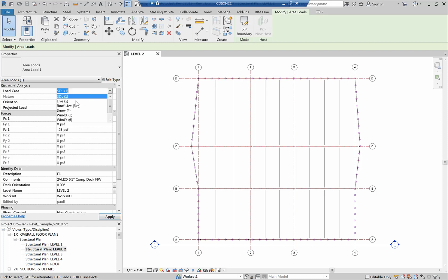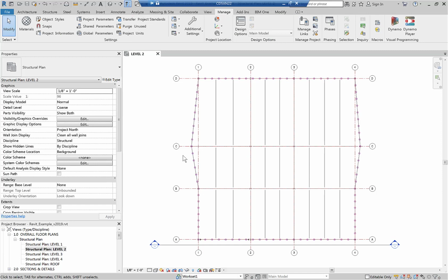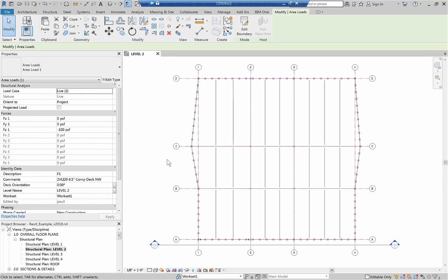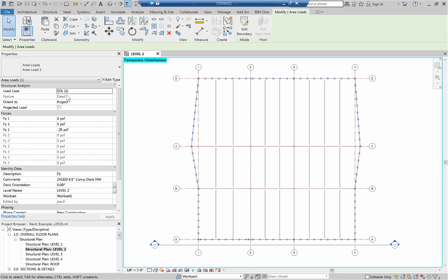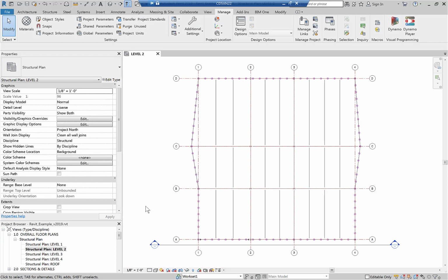And change the load case type, as well as the force value. Notice that we will not change the floor name in this case because the geometry is identical. Let's quickly verify that both loads are in plan. Hide the live load so that we can view the dead load. Let me show you what you need to do in order to have multiple loads on a level.